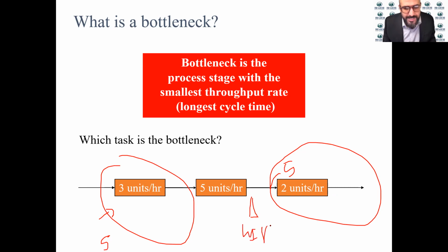Work in progress is not needed. This is bad inventory. We don't need the process work in progress. So the bottleneck is this one right here. What we should do from a continuous improvement perspective is investigate why this is the bottleneck. Do you need more workers? Do you need a newer machine? Is there an inspection needed before this? Or what exactly is happening? Your goal is removing the bottleneck.